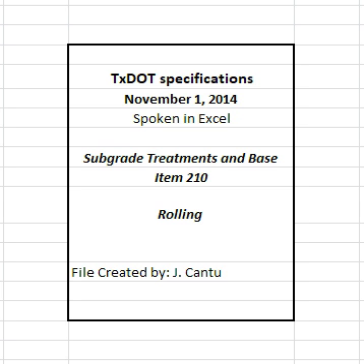2.2.2 Heavy tamping roller. Provide tamping rollers that have 2 metal tamping drums, rolls, or shells, each with a 60 inches minimum diameter and a 5 feet minimum width, or 1 rear and 2 forward drums, each with a 60 inches minimum diameter. Arrange drums so that the rear drum compacts the space between the 2 forward drums and the minimum overall rolling width is 10 feet.